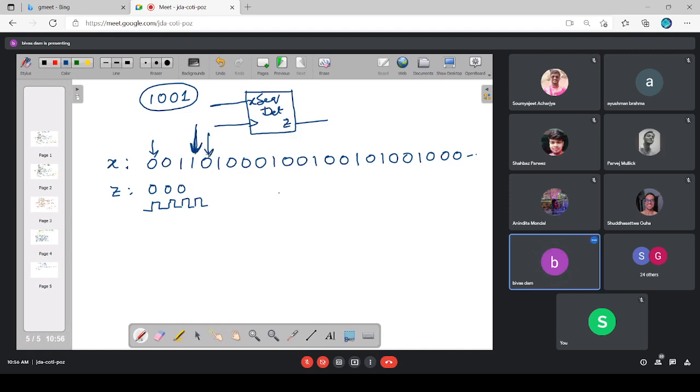When the next clock edge comes, I am having a 0. So what will be the inference? Second bit of the sequence detected. So when you go to the next state, what is the past history that you have? Two bits of the sequence are already available. So with that past history, I am going to the next time instant. There, what are you getting? A 0 or a 1? First bit again.